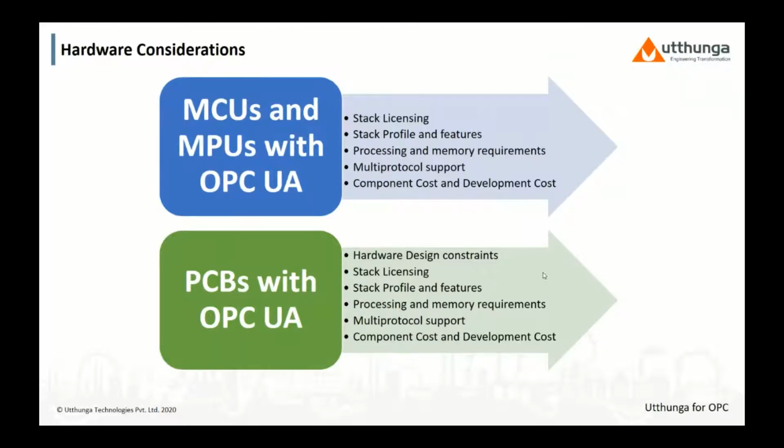When you are picking such a solution, you need to consider different aspects. Usually in such cases, the stack license still lies with the stack vendor, so you will have to get an additional license for your product line. But most of the hard work of porting to that specific controller and making it configurable and usable is already done. Then consider what profiles the stack supports, whether it allows you to flexibly switch between different profiles, what additional features it has, and what the processor and memory requirements of that specific bundled stack are.